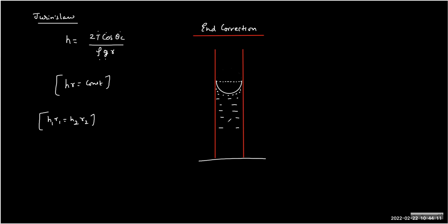What is the angle of contact here? In this case, the angle of contact is exactly 0, and because it is 0, the radius of curvature is r only. In this case, we should not analyze by the pressure method, we should stick to the force method.